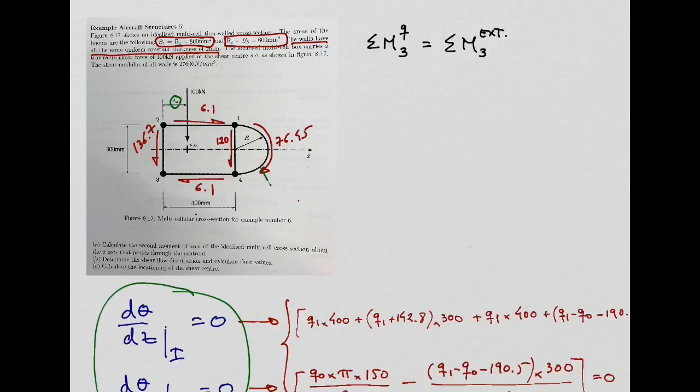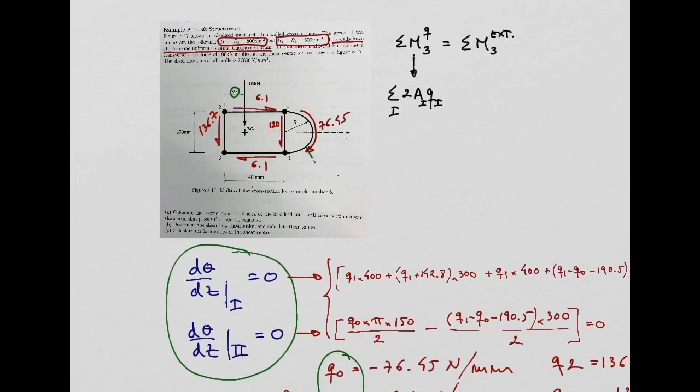summation of moments produced by the shear force about point 3 equal to the summation of moments produced by the external shear force. Don't forget this. The contribution for the moments from the internal shear flows we obtain from this expression: 2 times the area times the shear flow. Okay? Remember this? We did this last week, yeah? So let's start with...